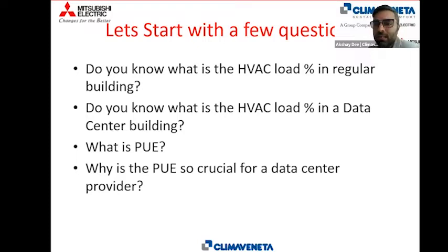Firstly, what is PUE? It's a term. Every product presented here today has a benchmark in terms of the performance of the product. It could be COP in a chiller or a precision unit, whereas in insulation, it could be the thermal conductivity. PUE is the measure of the efficiency of a data center. We call it power utilization effectiveness or power usage effectiveness.